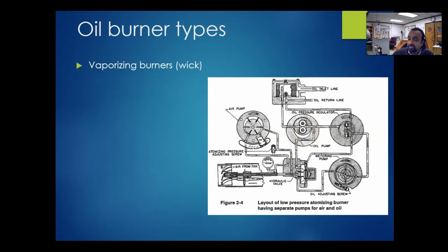There are also vaporizing wicks that do the same job as a candle or an oil burner with no pressure. They basically use osmosis to draw oil from a reservoir into the burning location. Some of them are also gravity fed, so you put the tank at a level higher than the wick and the oil just seeps through the wick and gets lit. There are issues with soot, of course, if the wick gets overfed or there's not enough air, so it's not as efficient, but it does still work, and in some locations it's still used when there's no electricity.